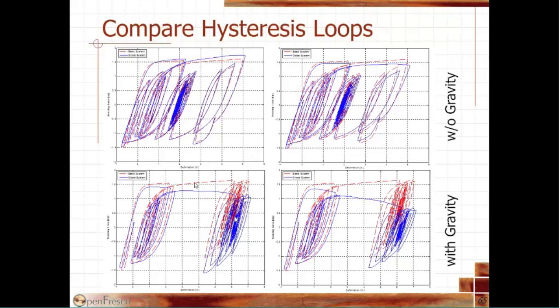And then once we superimpose numerically the second order effects, that will bring us into the global system. So if we look at those lines, the blue lines, you can now see how we can actually capture that second order effect and the negative stiffness in our hysteresis loop very nicely. So this was for how we simulate a control.